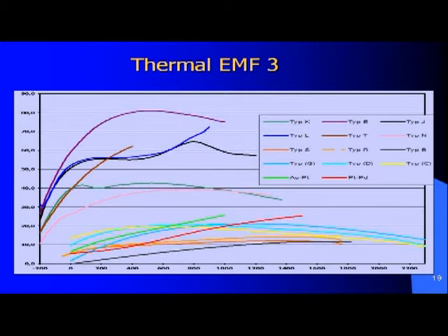And especially the platinum-palladium, it can be used up to 1500 degrees, but the palladium makes the platinum wire very coarse grain, and so it is sensitive to vibration. You must handle it with care. In my previous laboratory, we had both.